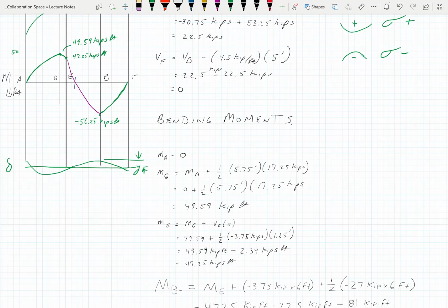So what shape of stress is on this beam? Negative. Now what do we do with this? Which side's in tension, which side's in compression? Top's in compression, the bottom's in tension, okay? And that's going to be important to you somewhere down the road in the future, okay? Not so much here in strength, but when you get to the design course, knowing whether your beam is like this or like this will play havoc with the rest of your design. Okay? Keep that in mind.